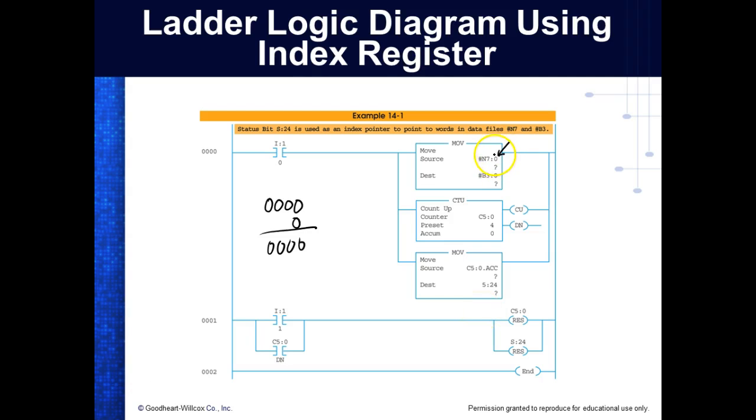But if I came over here and put like a 32, and my index register had a 63 in it, then what would be the address we'd be dealing with? Yeah, 95. But what we can do with the index register, guys, which is really clear, and we'll look at this, is it can automatically control this. We wouldn't necessarily use index addressing for something like this, but we would definitely use it for other features.